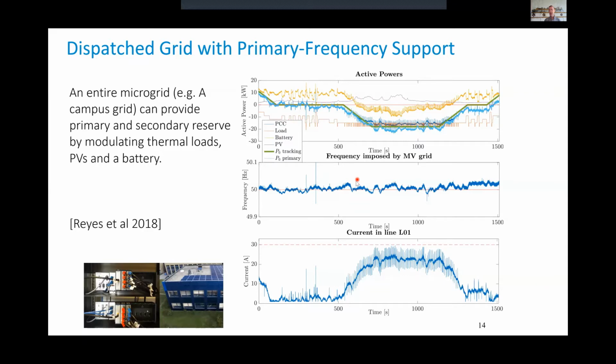This grid at this point in time was expected to do the green line, and we see it's doing the blue line, which is a bit less here. So it is consuming more than what it had advertised, because the grid is equipped with a regulator that monitors the frequency and instructs the flexible resources of the grid. Here there is a battery in this grid, but there might be also in some cases solar panels. This will be that you can curtail.